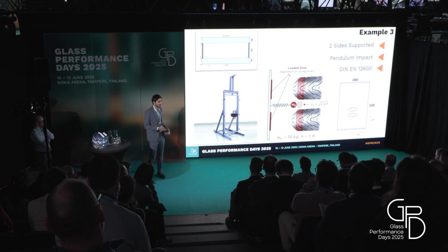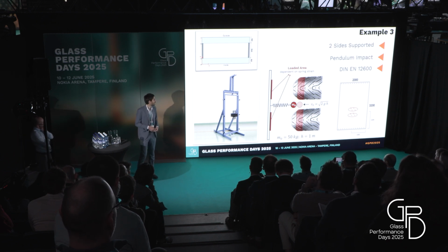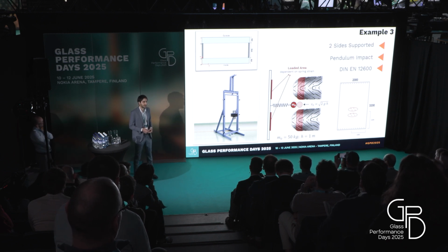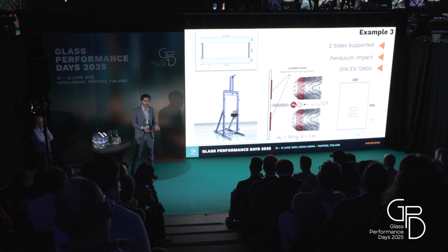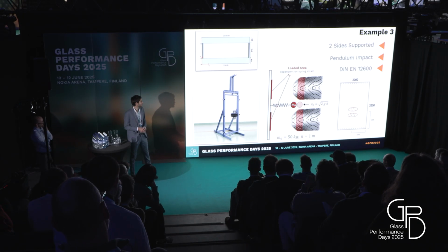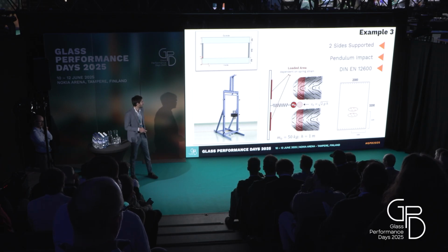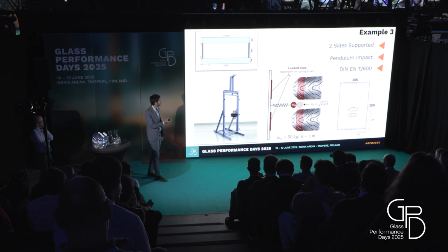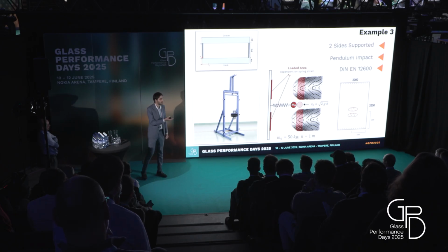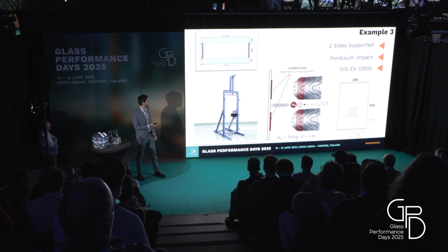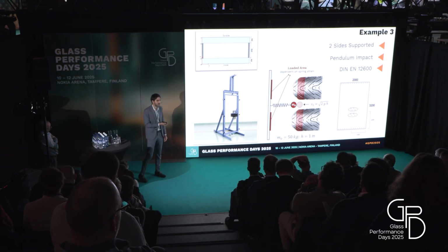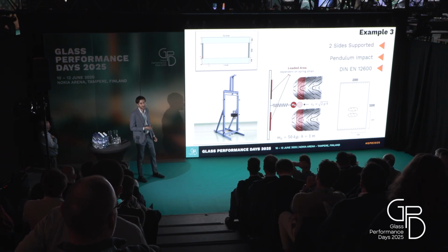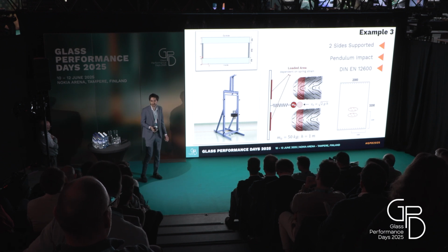It's a dynamical simulation, and so you have to take care of the loaded area of the tires. You have to calculate the displacement of an equivalent spring mass system and calculate the load on the glass surfaces. And this is done in exactly the same way as MEPLA does.